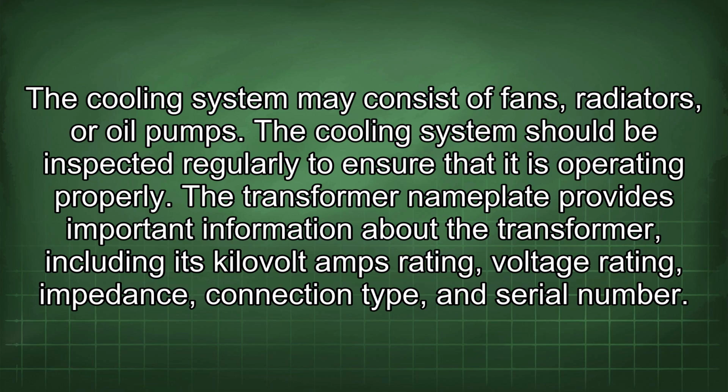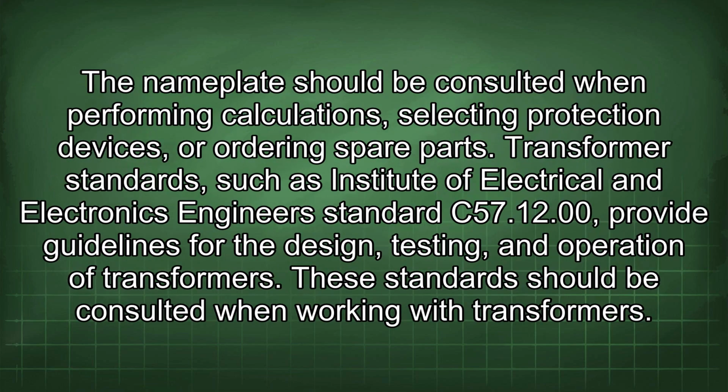The transformer nameplate provides important information about the transformer, including its kilovolt-amps rating, voltage rating, impedance, connection type, and serial number. The nameplate should be consulted when performing calculations, selecting protection devices, or ordering spare parts. Transformer standards such as Institute of Electrical and Electronics Engineers Standard C57.12.0 provide guidelines for the design, testing, and operation of transformers. These standards should be consulted when working with transformers.